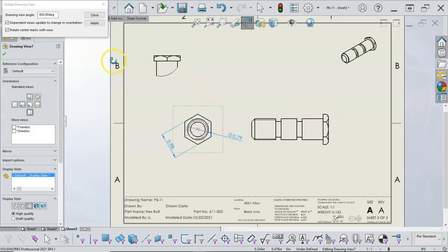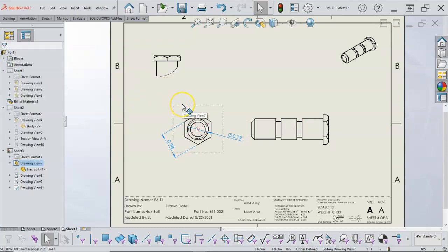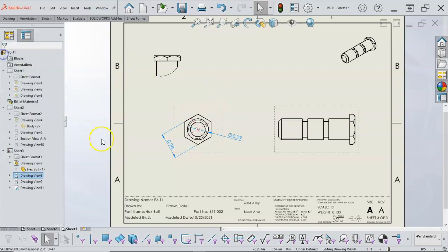So both of those work, but notice all my dimensions disappeared when I did that rotate after I applied them. That's always the warning with it. All right, so again, take the drawing to whatever level you're comfortable with, and then basically be able to create the views, apply some dimensions, and we'll work and build out from there.